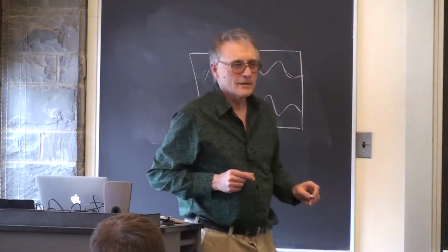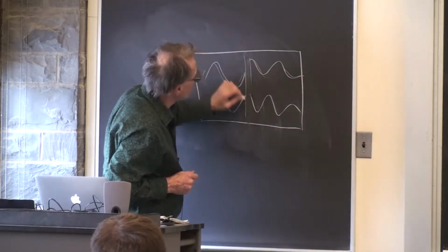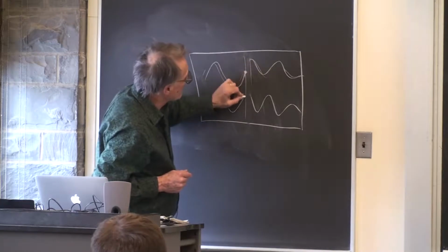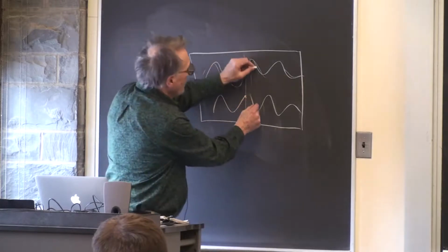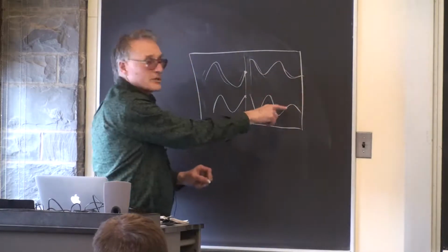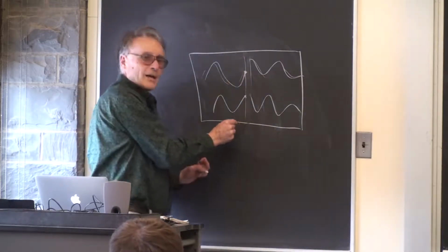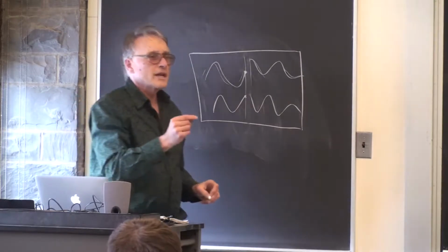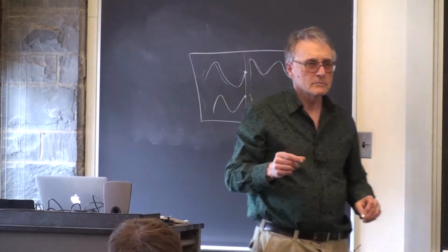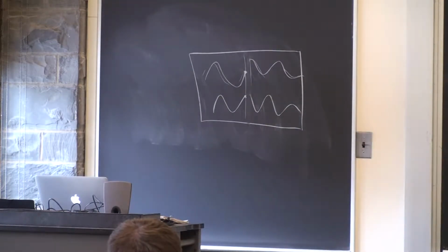It actually erases a little vertical bar all the way across the screen. So when you're rewriting this point, the 10 pixels or so in front are erased, and then the old waveform is over here. And so what you could do is write a thin black rectangle on the screen just ahead of the point you're plotting. Maybe only 1 line wide, but probably 2 or 3 lines wide.